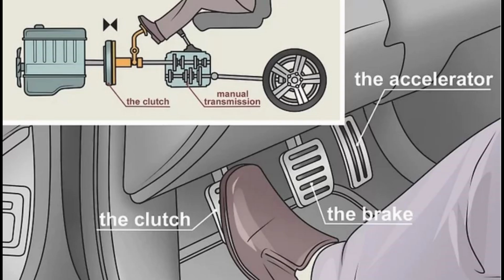Different gears vary mainly in their gear ratios, size, and function. The gear ratio determines how many times the engine rotates for each rotation of the wheels. Lower gears have higher gear ratios, meaning the engine turns many times for one wheel rotation, providing high torque but low speed. Higher gears have lower gear ratios, allowing the vehicle to move faster with less engine effort.